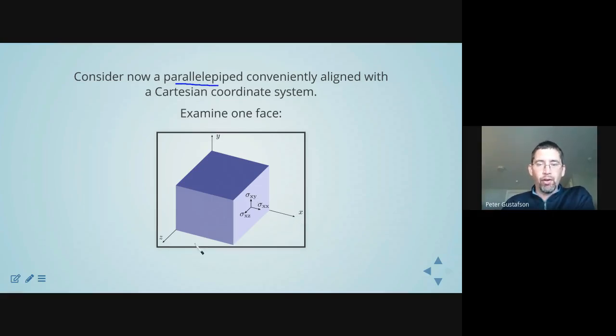Now, by taking these imaginary cuts, this parallelepiped has 6 internally exposed faces, and load is passing through the faces of the cube. You can think of the external tractions of the cube as being the boundary conditions on the cube with load passing through the cube.